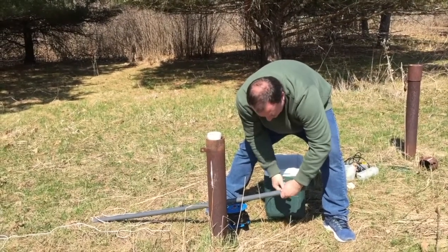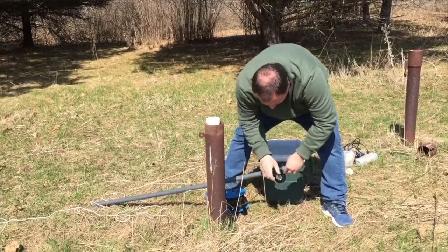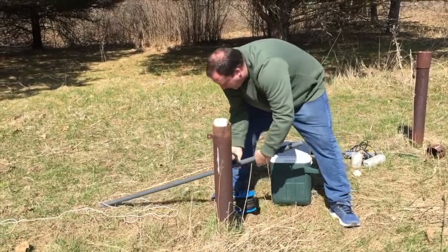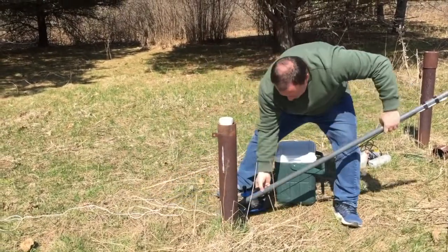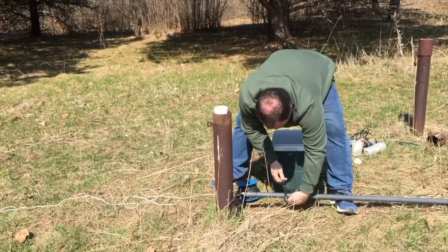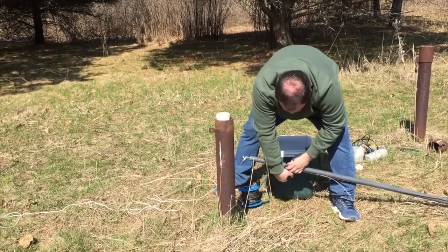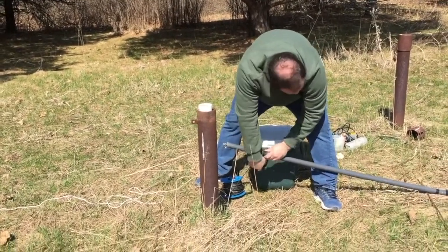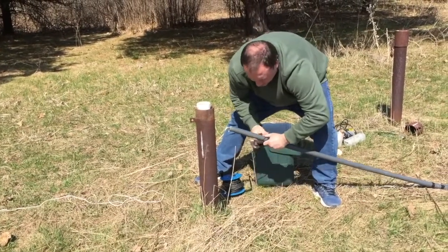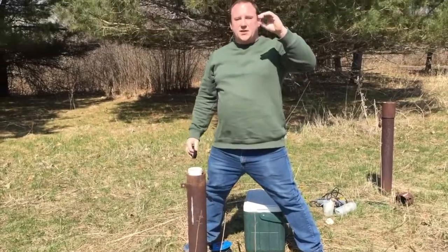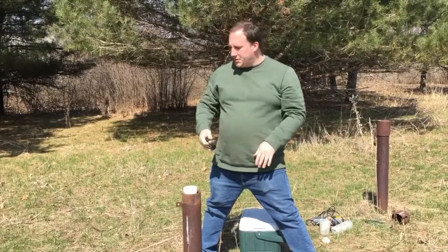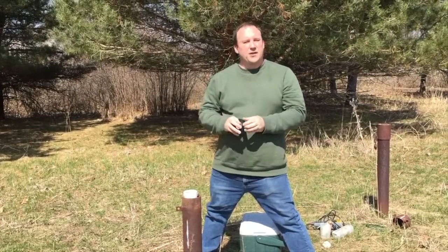You want to make sure that it's on here tight enough that the water level indicator doesn't get any bending or scraping or anything like that. We want to make sure we tape the end of the line here in a couple of places. The exact depth and location on here isn't important. I just need to know that I'm close to the water table and that when I drop it in, I'm fully submerged into the rope section. That's all that really matters.